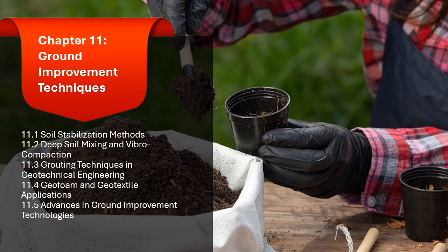Deep soil mixing, DSM, is a ground improvement technique in which binders, usually cement, lime, or other stabilizing agents, are introduced into the soil at depth by mixing them with the native soil.